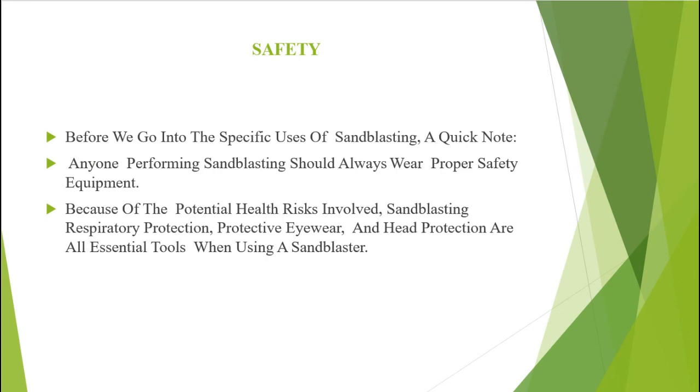Safety. Before we go into the specific uses of sandblasting, a quick note. Anyone performing sandblasting should always wear proper safety equipment. Because of the potential health risks involved, respiratory protection, protective eyewear and head protection are all essential tools when using a sandblaster.